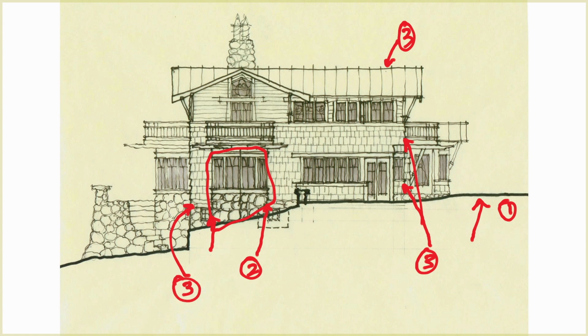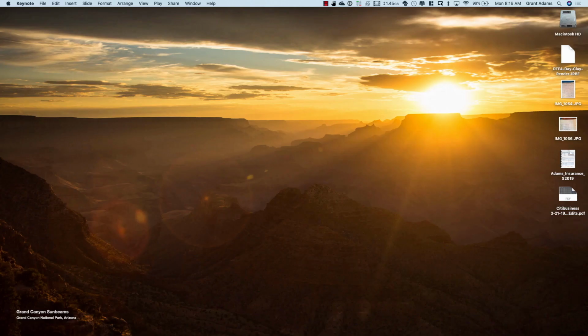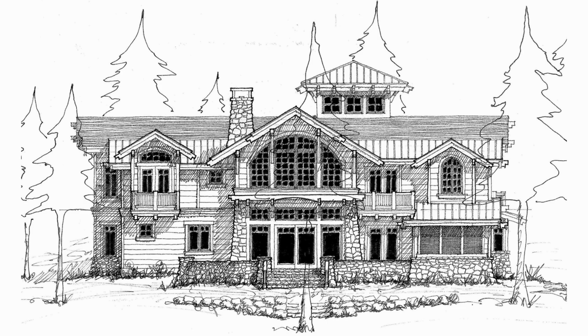Then we keep going backwards. We might get more detail like the doors, this window edge, that might be number 4. These textures start to be maybe number 5. That texture is probably number 5, etc. Do you see how I'm working my way down? A good drawing tends to have at least 5 line weights. It's a good rule of thumb. More is always better, but I would say at least 5. So let's jump into the next slide.